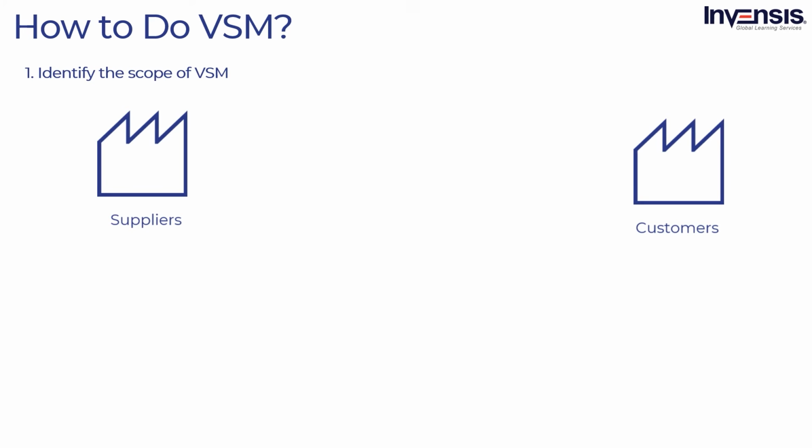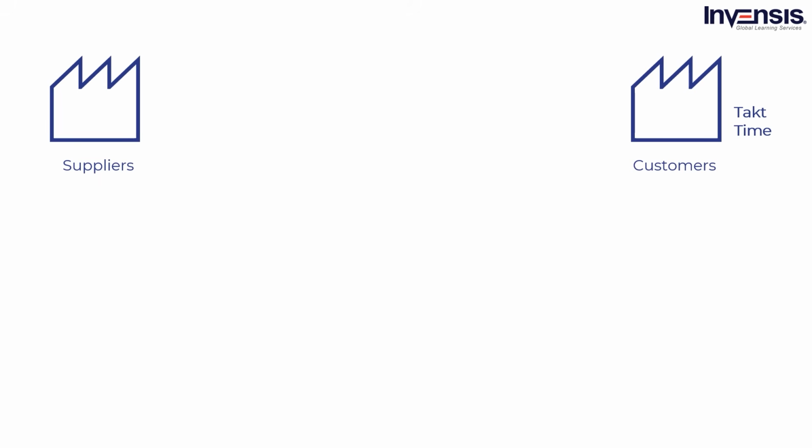Now, next to the customer, record your takt time. This is the maximum span of time you can spend while still satisfying customer demand. It is easy to calculate this number. Just take the available minutes for production and then divide it by the required units of production.